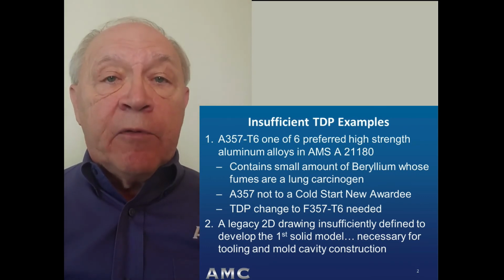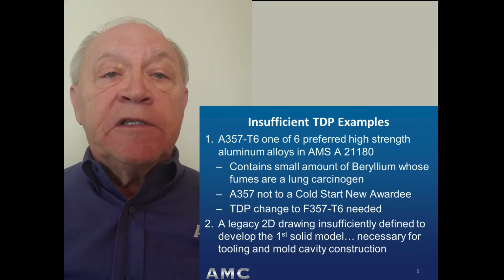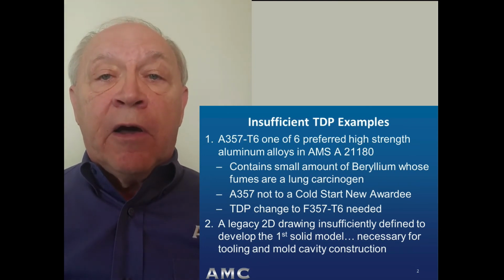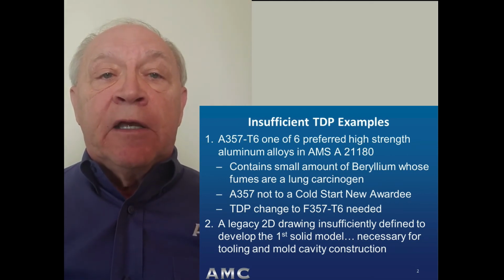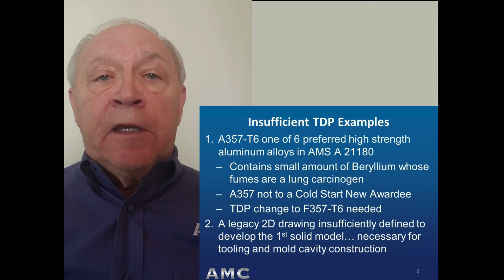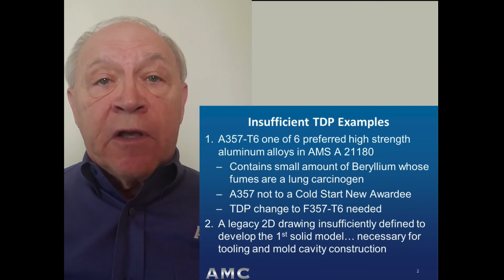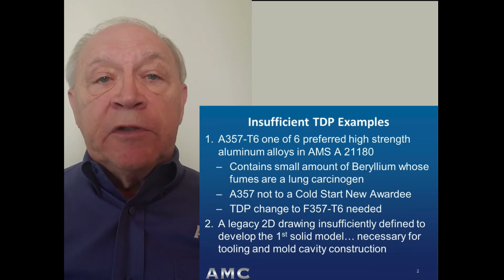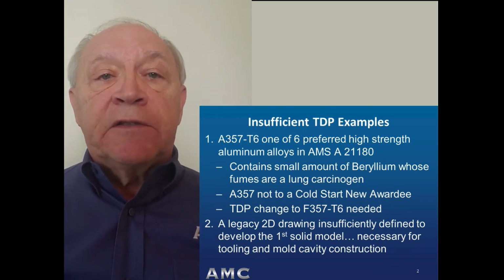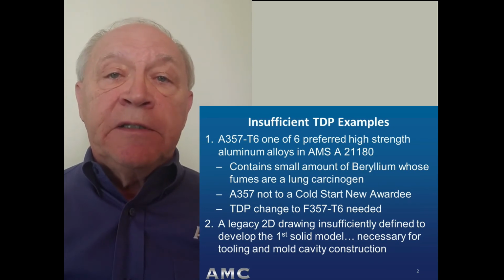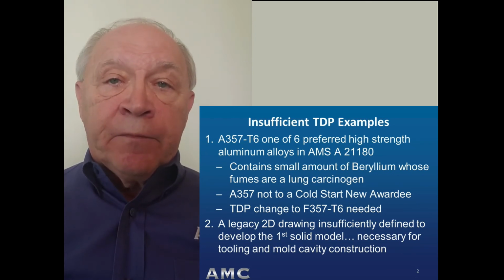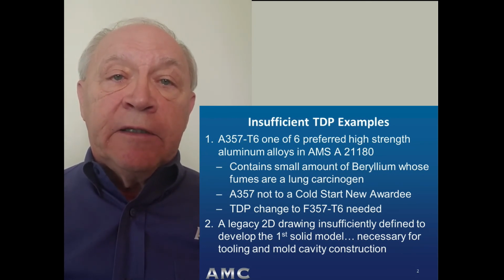A second example, the drawing dimensions are insufficient to fully define the solid model that the mold cavity tooling builder always creates at the start of new tooling construction. Everything now starts with a solid model. Originally, when tooling was built by hand, the pattern maker, as they were known in those days, used latitude to blend together the features that were insufficiently defined dimensionally, resolving the issue with a blend.